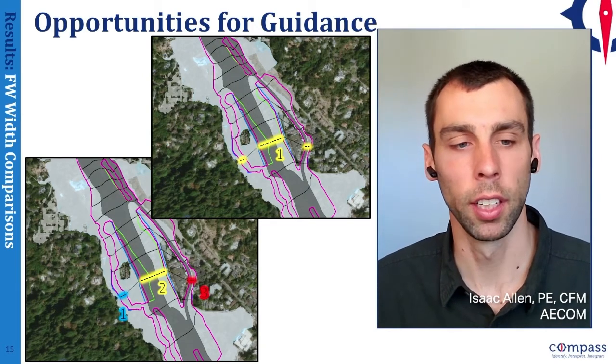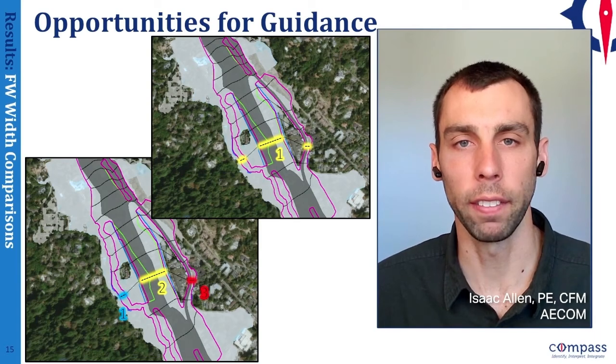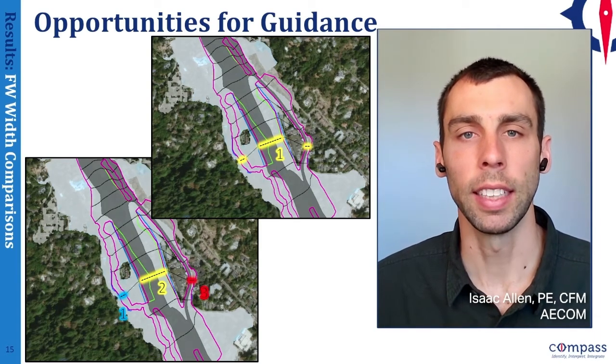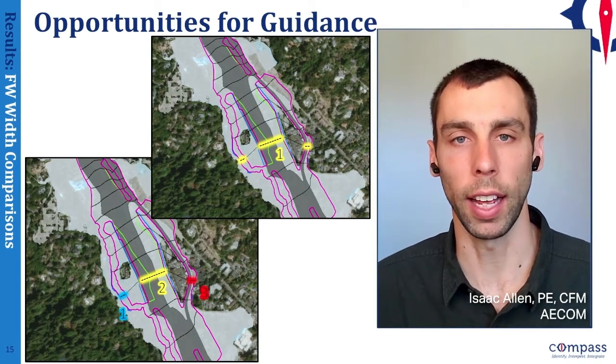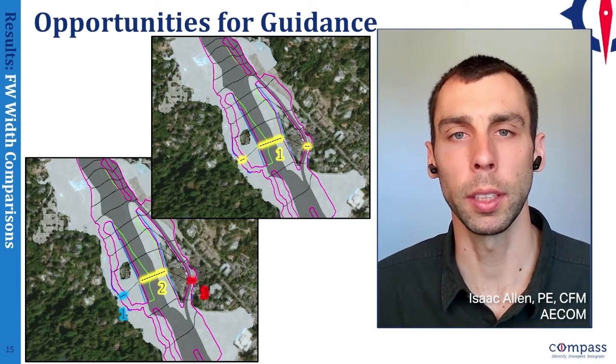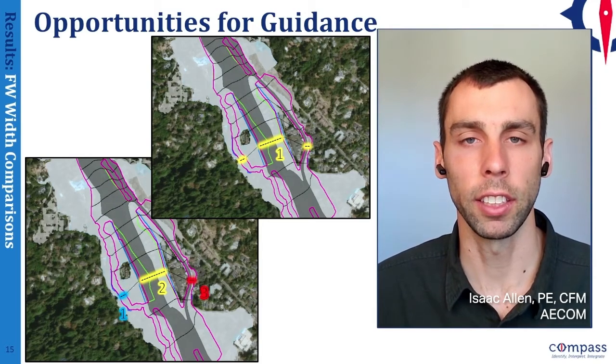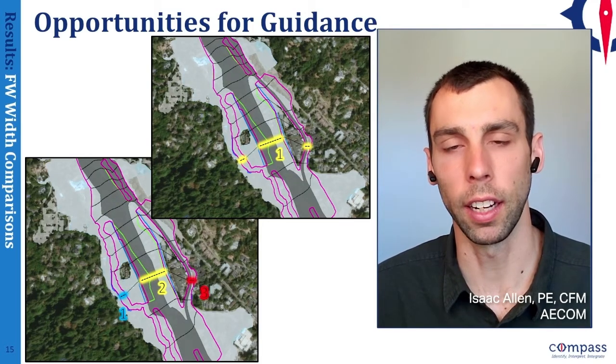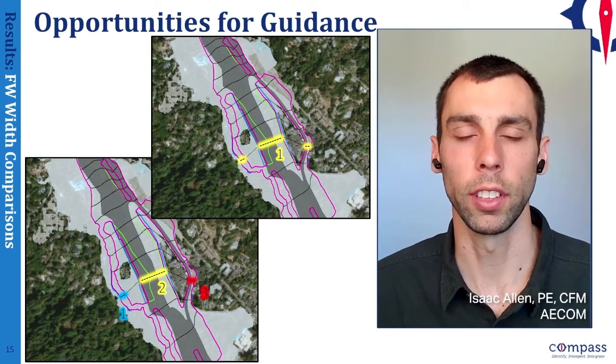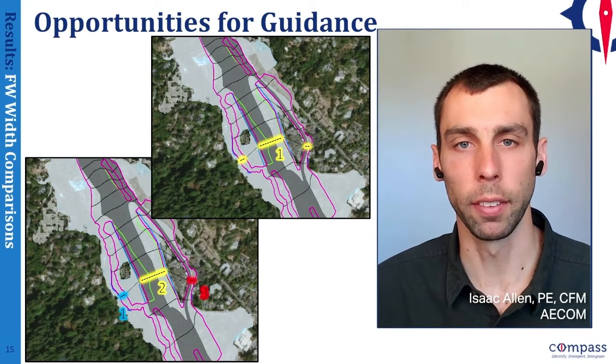The second approach, which is shown on the bottom left of this slide, is to break up your average into essentially 3 independent evaluation lines. This approach is preferred because it does not allow the surcharge average on one of the reaches to influence another and therefore result in a narrower floodway than you should have.